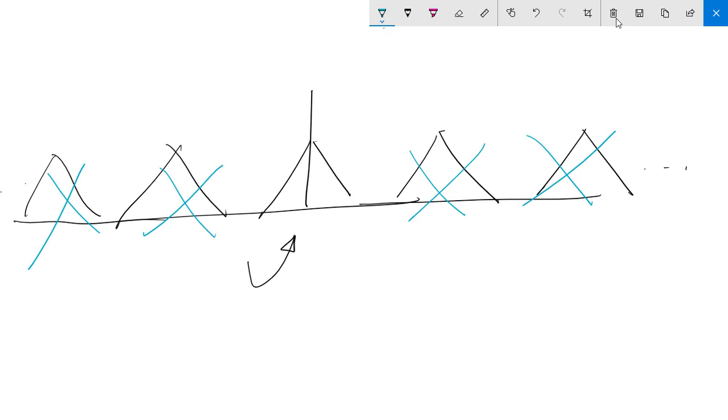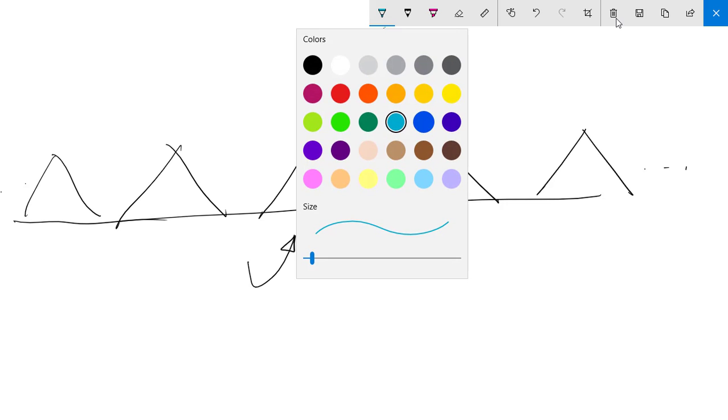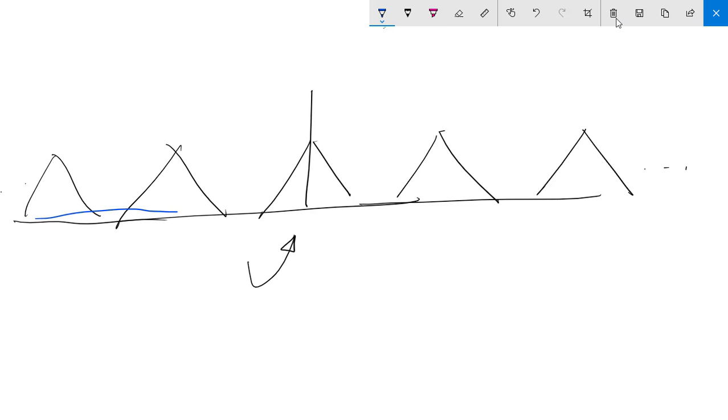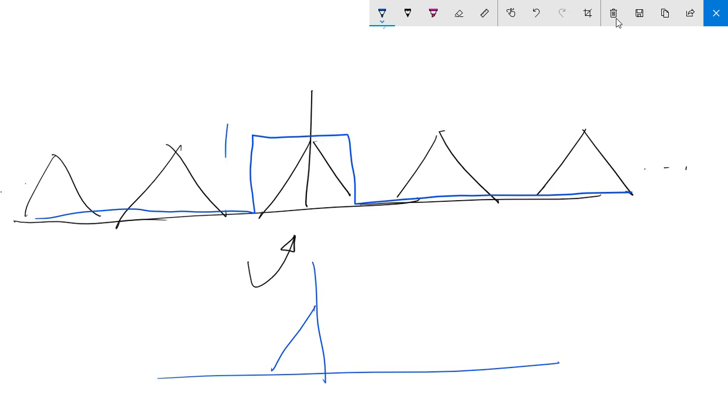But cutting off is not this easy in Simulink. What we need is something that will filter only this part out. That is a low pass filter. You need a low pass filter which is something like this. Multiply them. Here it is 1, so in this portion you will get the output equal to the input, and in this portion it is 0, so you will not get anything. So this is our reconstruction in the frequency domain, and this is enough for retrieving the time domain signal.